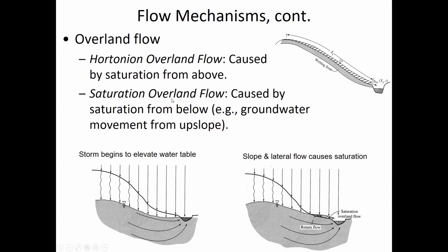And it seems kind of strange that they call it overland flow, but the point is that it's a lot faster than just the base flow that takes many days after a storm event to continue draining out of the soil. You push the rain in here, and some of it comes out faster downstream. It's not necessarily the same exact particle. It's just by raising the water table on one side, it exits more quickly at the other. So I guess that's why they're calling it overland flow, is not necessarily because it is directly flowing over the surface, but because of the speed of it being relatively quick.